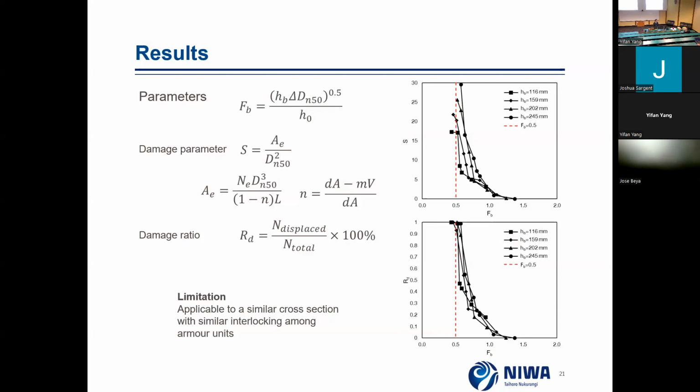I'm not sure. Can't we just extrapolate this result to that? So we can assume the first one does erode some armor layer, then we can use the second one as a single wave, which erodes from here. So can't we just extrapolate these results to a train instead of considering a train? So the first wave comes, maybe it does 20% erosion. Then you consider the eroded one as the breakwater. Then you consider the next wave. Then like that. We can just extrapolate this, right?